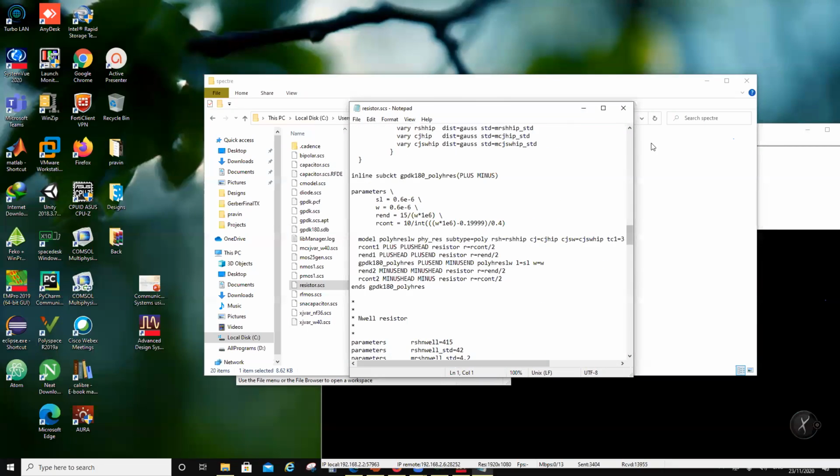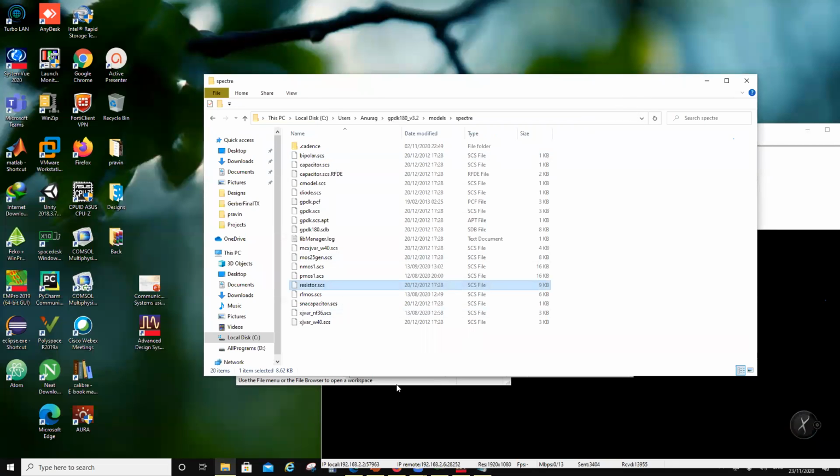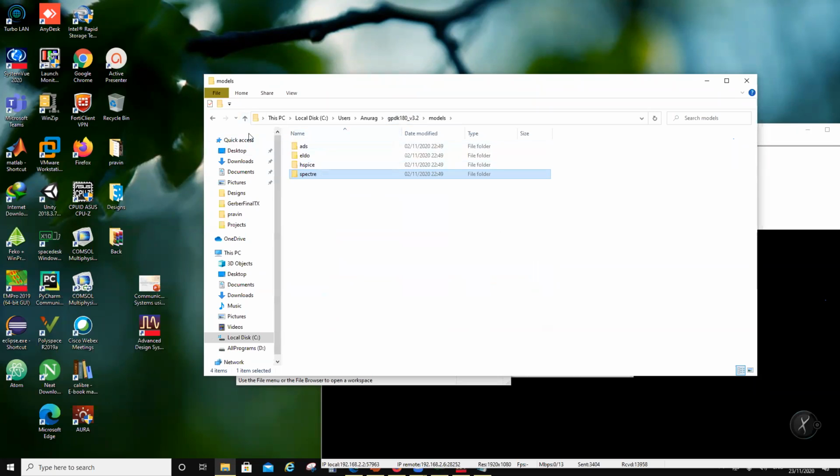Now before you touch any of this, there would be something called restrictions, in the sense that when you do DRC, there will be DRC rules. Now if this is a 180 nanometer process, that means the minimum gate length is 180 nanometers. Now I decide I want to do 90 nanometers because my model is 90 nanometers. Then you should see where the switch is, in the DRC rule file. So the switch is somewhere here.